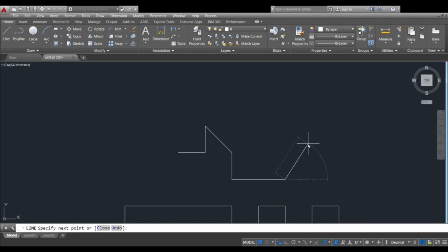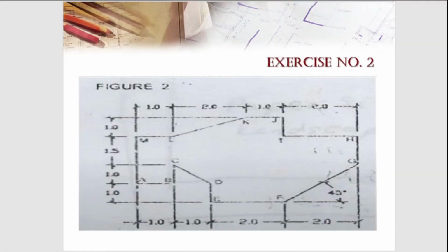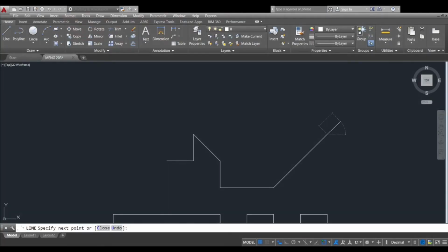So let's try it in CAD. At 2.8284, angle 45. Okay, so that is our point G. Going to H, that is 1.5 units going up. So that is 90 degrees. So don't forget to put at angle 90 degrees. I input the wrong one. So at 1.5, angle 90 degrees. Okay, just 1.5.